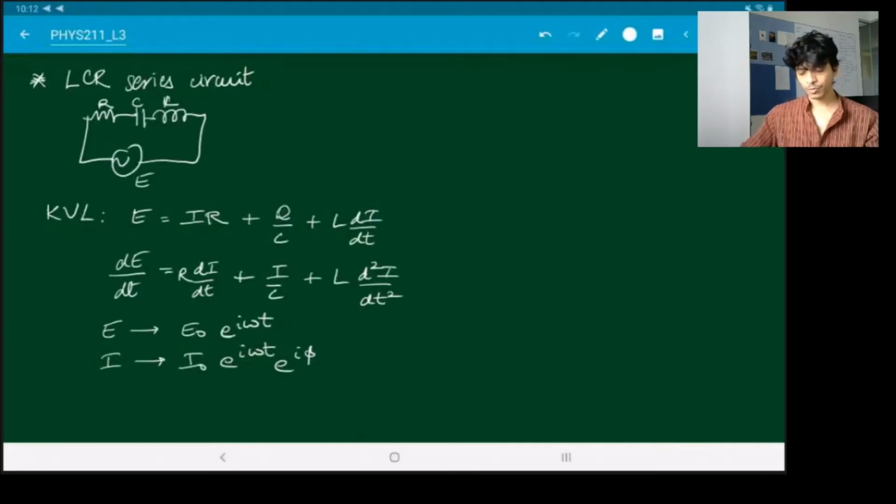Okay, let me go back one step. So whether I write, I'm free to write my voltages and currents either as sine waves or as cosine waves, because they're just a shift in 90 degrees. So I can either choose to do my analysis with the real parts or the imaginary parts. Real parts will give me cosine, imaginary parts will give me sine. So over here, because consistently we've been doing sine omega t waves, we are talking about taking the imaginary part.